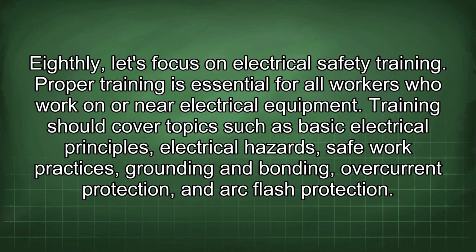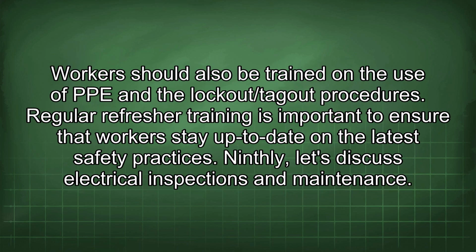Eighthly, let's focus on electrical safety training. Proper training is essential for all workers who work on or near electrical equipment. Training should cover topics such as basic electrical principles, electrical hazards, safe work practices, grounding and bonding, overcurrent protection, and arc flash protection. Workers should also be trained in the use of PPE and the lockout/tagout procedures. Regular refresher training is important to ensure that workers stay up to date on the latest safety practices.